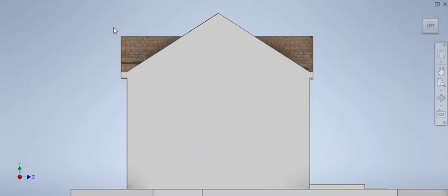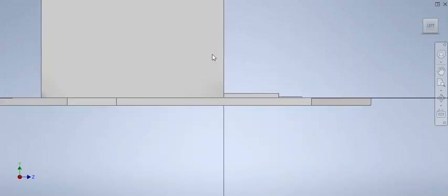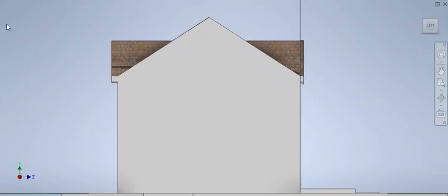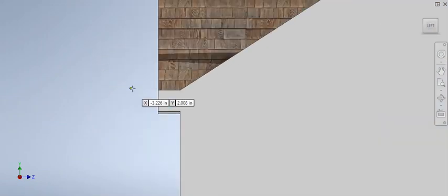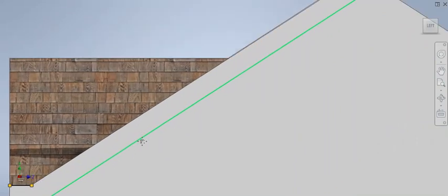Hi everybody, I'm going to continue demonstrating how to generate the trims around the house on the side of the house. This is a 3D printed residence, and I'm going to select the surface of the gable end of the house. After clicking on the surface and the plane has been selected, I move my cursor over create sketch, and that enables me to select the line command, and I can now select the lines to create a trim.